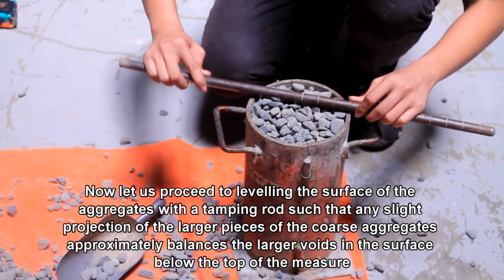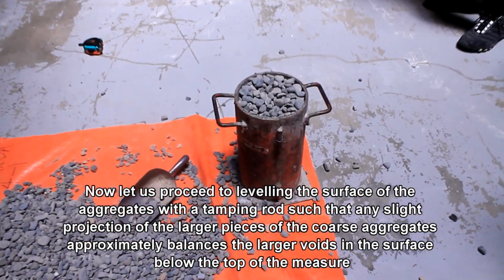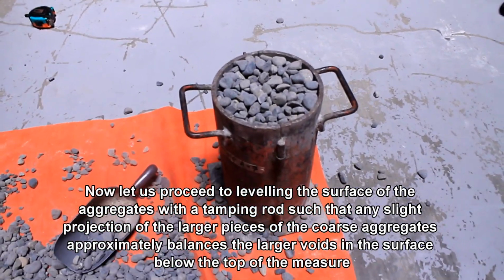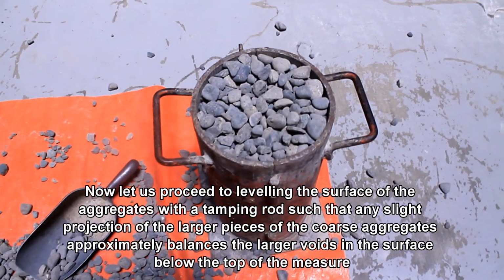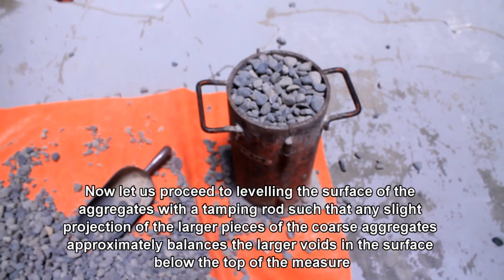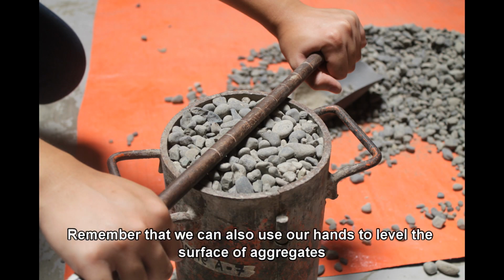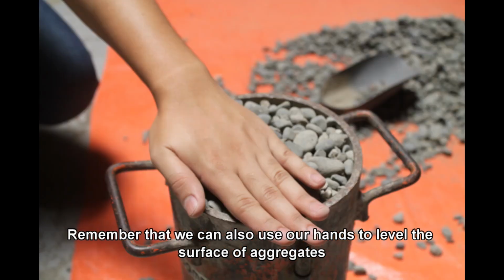Let us proceed to leveling the surface of the aggregate with a thumping rod such that any slight projection of the larger pieces of the coarse aggregate approximately balances the larger voids in the surface below the top of the measure. Remember that we can also use our hands to level the surface of the aggregates.